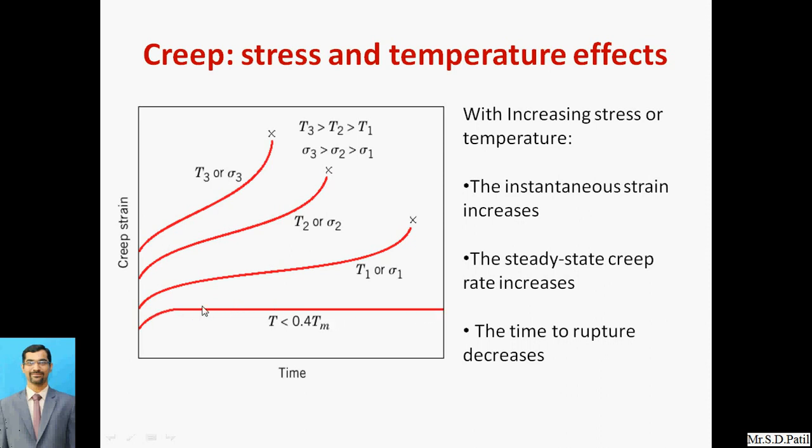Here we can see the strain is constant and time is constant. If the temperature keeps increasing, then rupture will occur. When we increase the temperature, here we can see T is at the lower side of the threshold temperature of creep, then T1 is increased over T. How will the rupture occur? If we increase the temperature again, the stress will be increased and rupture will occur shortly.